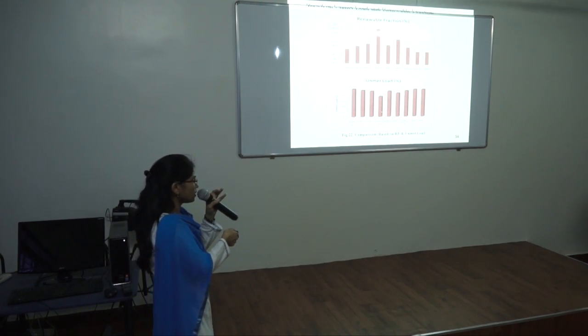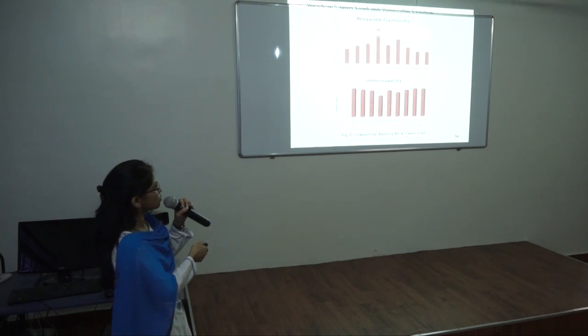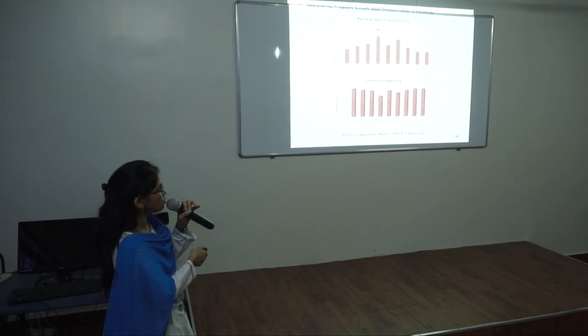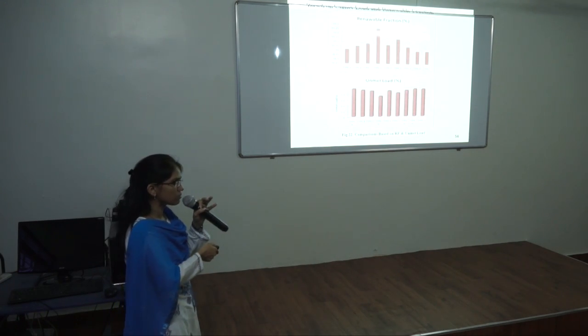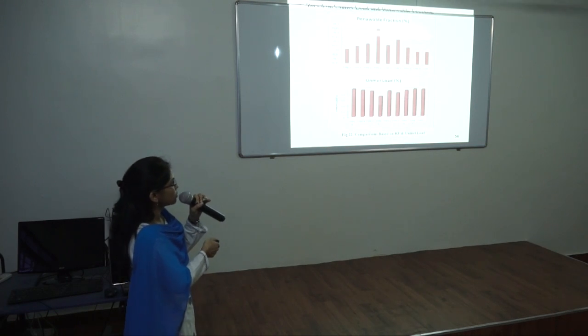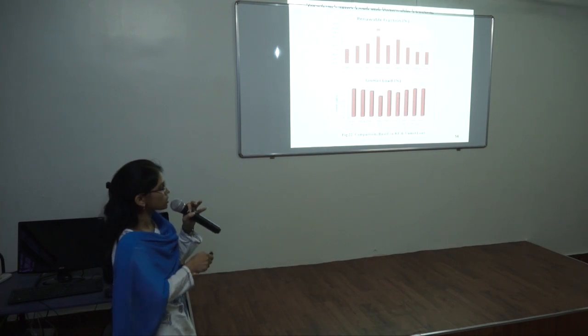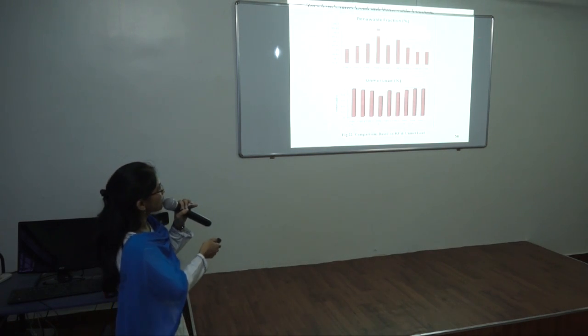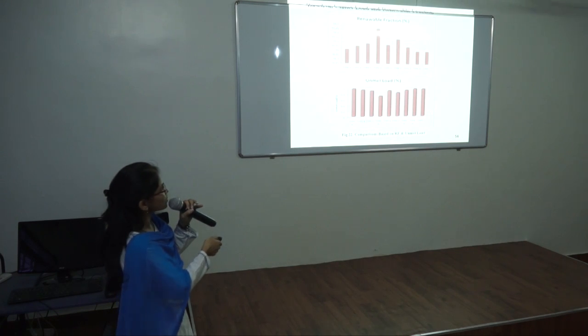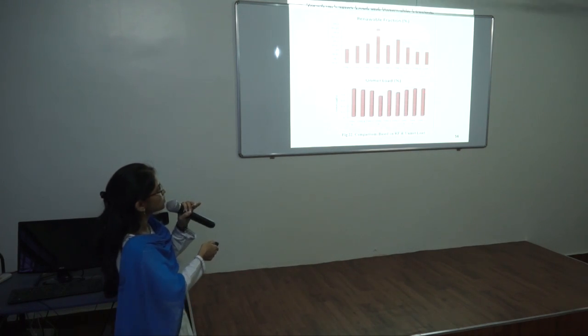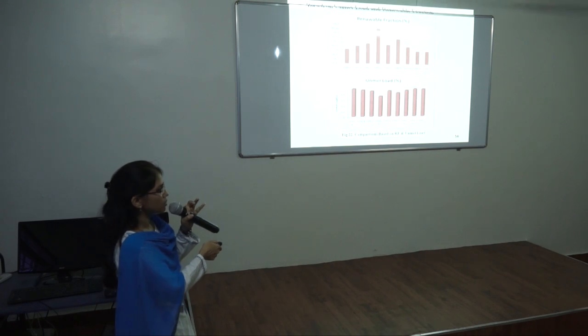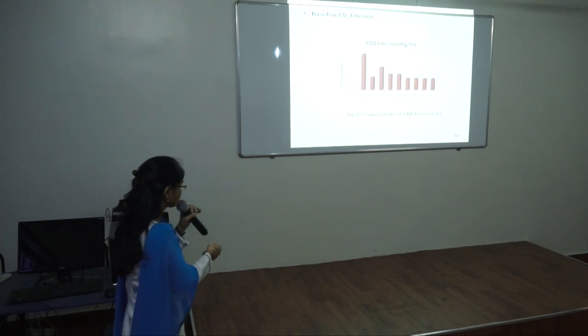But as explained earlier, by considering the renewable fraction and unmet load, the maximum renewable fraction and minimum unmet load is a good choice for reliable power supply. But such architecture will require high investment, and in such case the selection criteria is based on compromising the cost and minimizing the environmental pollution. And from that, type I is chosen as the winner of the optimization by considering the renewable fraction above 99%, with minimum net present cost and cost of emission.